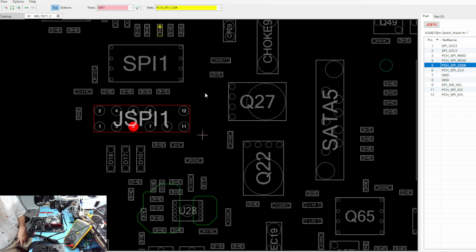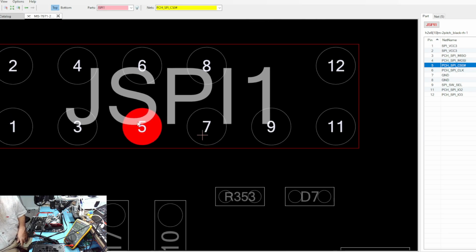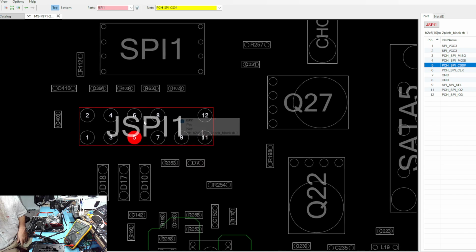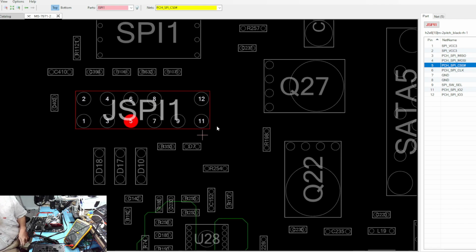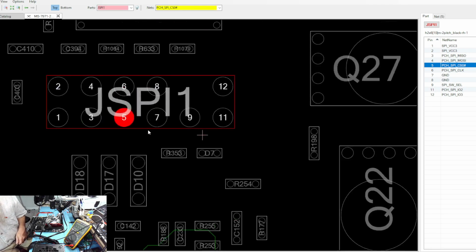So the signal is only relevant if our CS pin changes. I think it's high by default, and to wake up the chip, to tell the chip that I'm talking to you right now, the CS goes low. Or the other way around, I actually don't remember. It's not relevant, because what we want to see is on this pin, we want to see some signal. So that's the third one from the left.